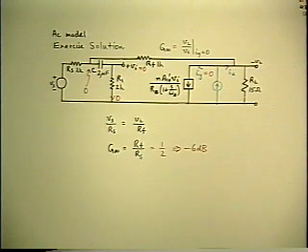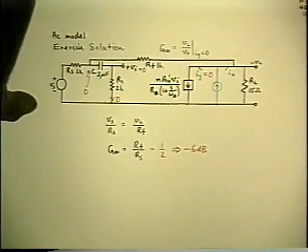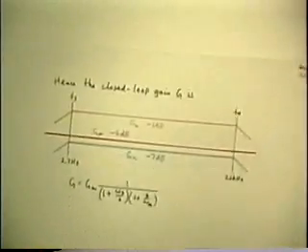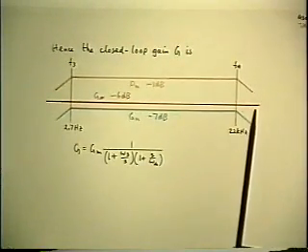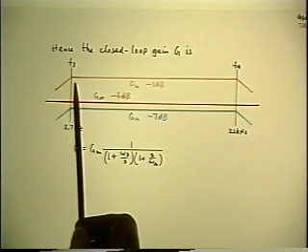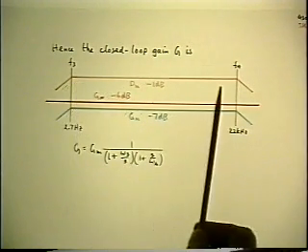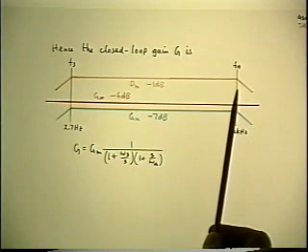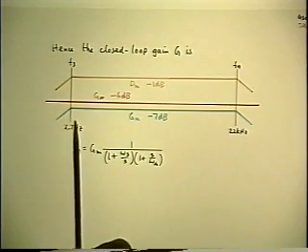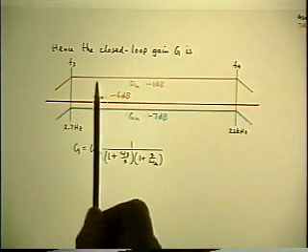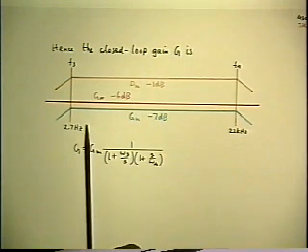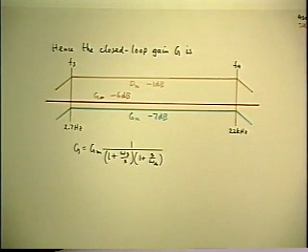Okay, that's the other part of the solution. You can see that's pretty simple. And the last step is just putting together the two pieces. The G infinity is constant at minus 6 dB, and the D we've already found, minus 1 dB with a pair of poles. So the actual closed loop gain is the product of the G infinity and the D, which is the direct addition on the dB graph. That gives you the green line.